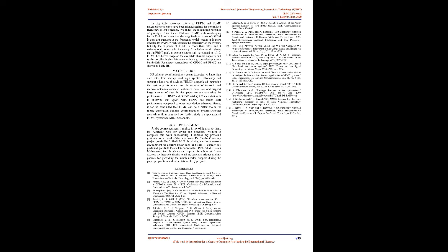Fig 4 and Fig 5 represent the spectrum of OFDM and FBMC, which shows that when carriers are modulated in OFDM, side lobes spread out on either side. However, in FBMC with a filter bank system, the filters are used to remove the noise. Therefore, in FBMC we get much cleaner carrier results. Also, FBMC provides high spectral efficiency and data rate. FBMC is more spectrum efficient than the OFDM system. The cyclic prefix required for OFDM is not needed in FBMC, thereby freeing up more space for real data.